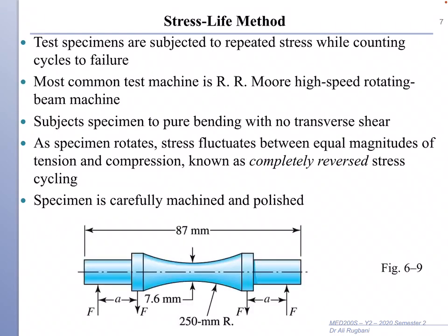Okay, so the experiment that we're going to use is simply we prepare a specimen that is carefully machined and polished with standard size. We actually need many specimens to run one experiment. This test specimen is subject to repeated stresses, and we must count the number of cycles before failure